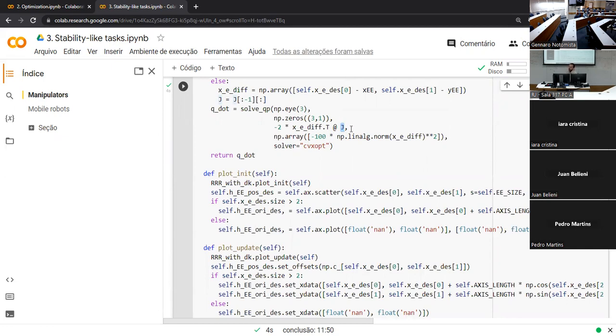That's actually not just a simulation problem, because all robots work in discrete time. So you need to make sure that these parameters, for example this multiplier here, are not large. Otherwise, you will actually get instabilities in your system.